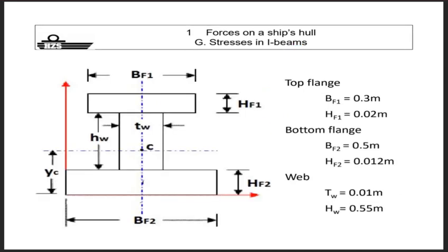So this you will need. You will get a distribution, a cross section, and you need to calculate the moment of inertia. Of course, it will be step 1. If not, you're not able to come up with stresses. So it will be part of your third exercise, and then you have multiple exercises within the course. For this, you need to calculate the position of your neutral axis. Are you able to do this? Calculate the position of the neutral axis of this I-shaped beam?